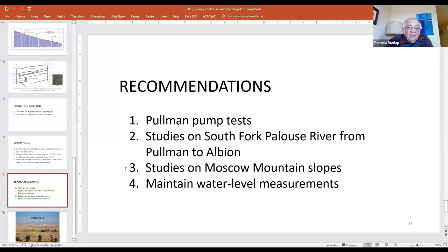It's thickly covered with weathered granites and Quaternary sediments, but I believe you could find some other areas and only have to do shallow drill holes to verify that there's recharge. And maybe some of those areas can be easily changed to accommodate extra snow melt, extra runoff water. There's a lot of ponds and poor drainages up there. So I think that area should still be looked at as a potential area for increasing our recharge.